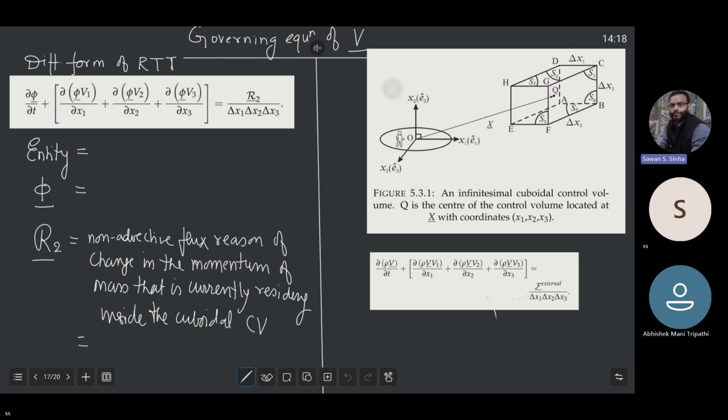If you talk about momentum, all taps closed, this much momentum is in the full fluid. At the next time instant, will that momentum change or not? It's governed by what? There is an axiom which tells me how the momentum inside the control volume will change because of non-advective reasons. You draw the free body diagram: the net force acting on the mass that is inside the control volume. That's the mechanism by which nature generates more momentum.